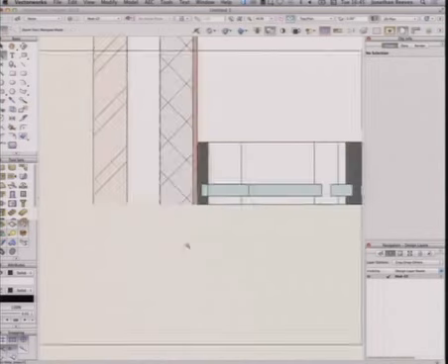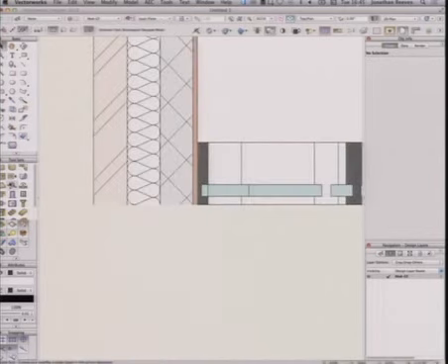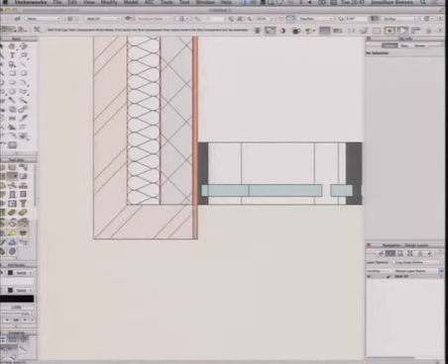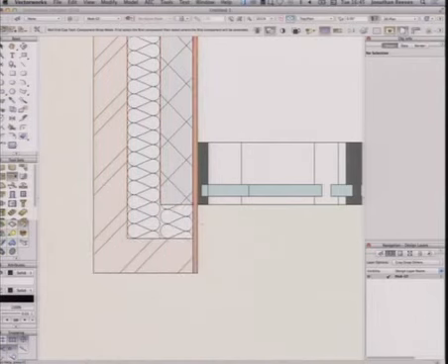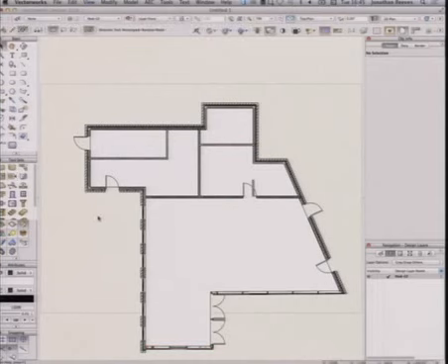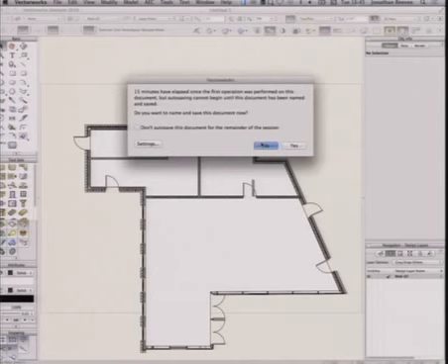So without the auto-join, it doesn't join. And then I would get my capping tool, this tool here. And essentially, I would just cap the construction round to decide what kind of junction I wanted there. And go into that in a little bit more detail. Okay? So the auto-join, sometimes you want it on, sometimes you don't. Okay, right, let's motor on.